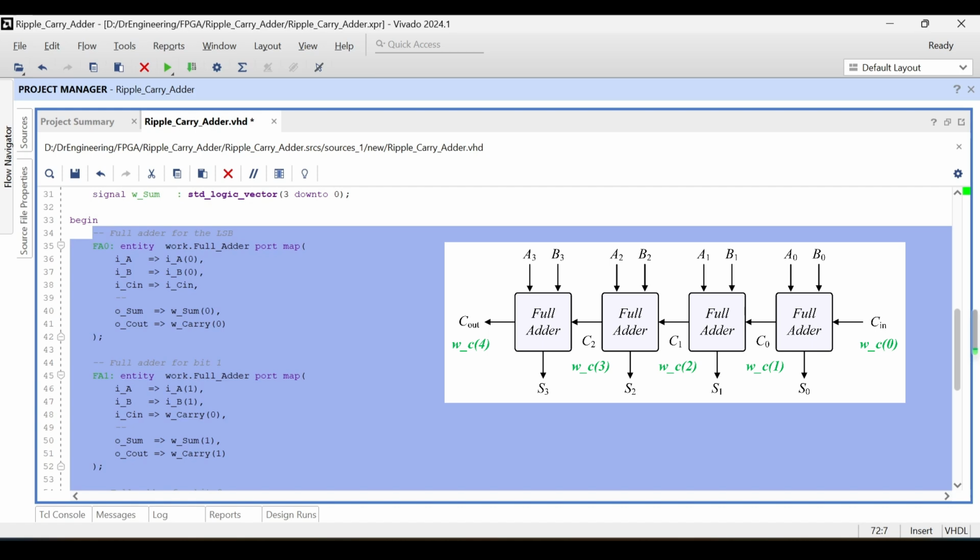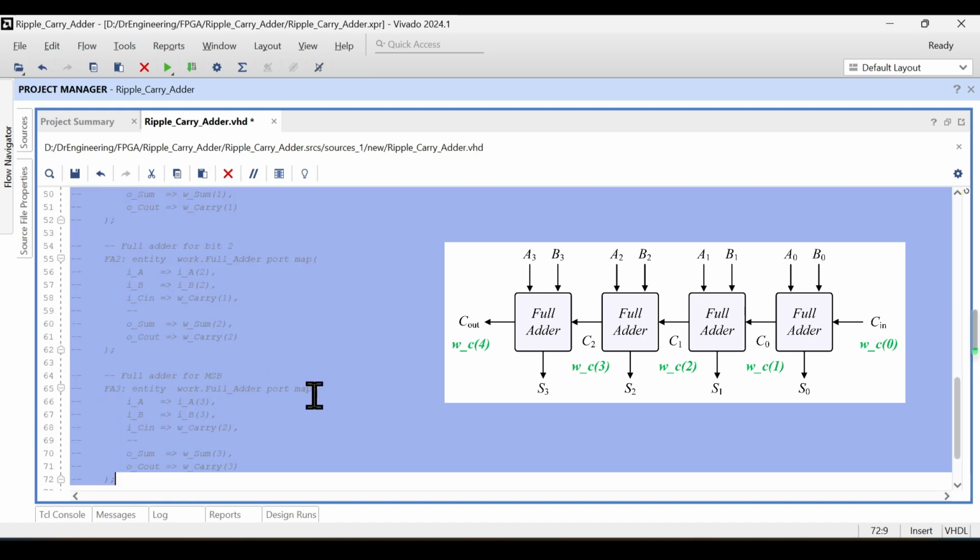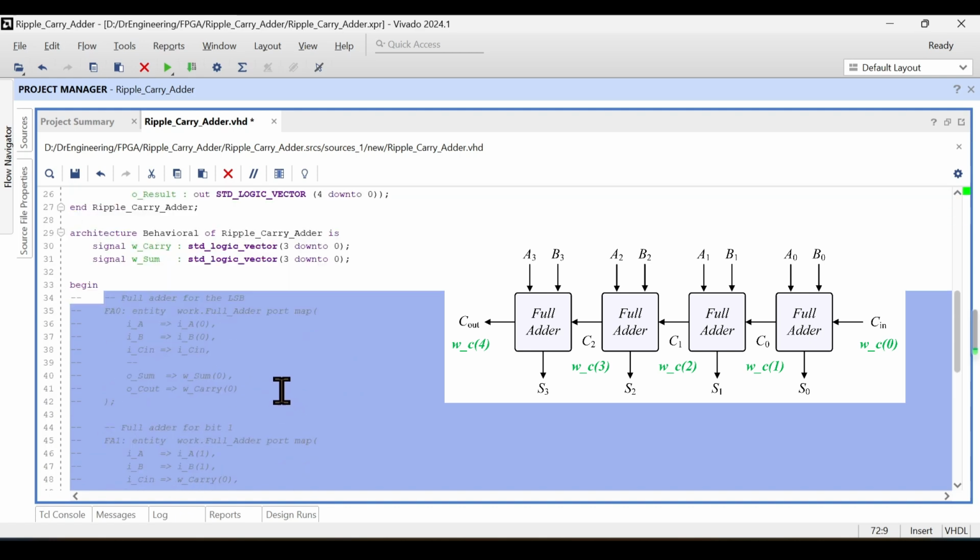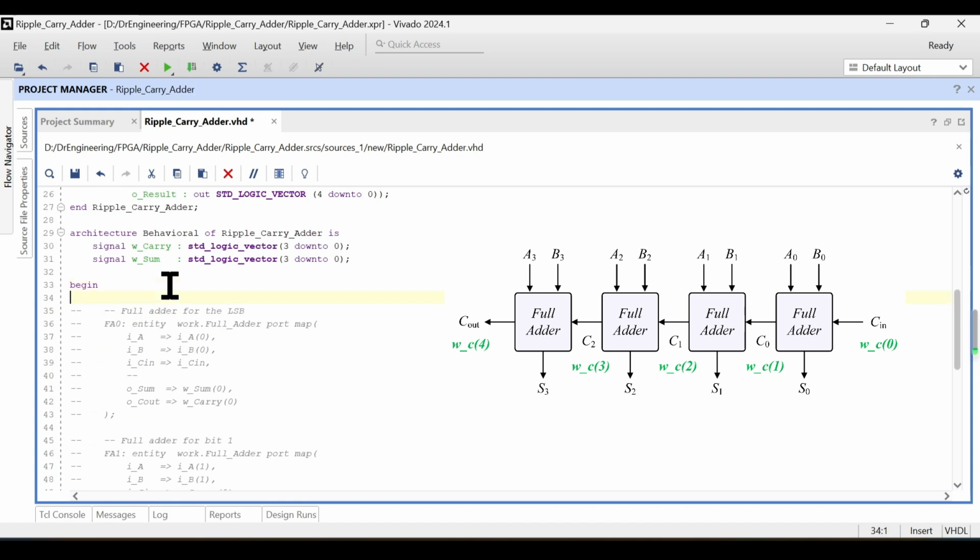Based on this new schematic, we can now use a for loop and generate statement to define multiple full adders. First, we'll comment out the previous full adder declarations. Then, we'll copy down the parts we'll still need. Using the forGenerate syntax that we just introduced, we define the label as set_fa, which represents that we are defining multiple full adders here.